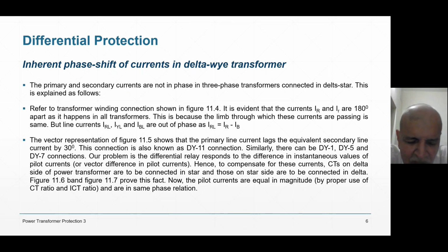Second harmonic will be there if the core of the induction motor, core of the transformer, core of the generator rather saturates. That is a different thing. Otherwise, first, third, fifth, seventh, up to seventh, they are quite large. Beyond seventh, probably you may forget, because it would be in terms of 0.5% or 0.1% or 0.12%. But third is so often 18% or 19%, which you cannot forget.